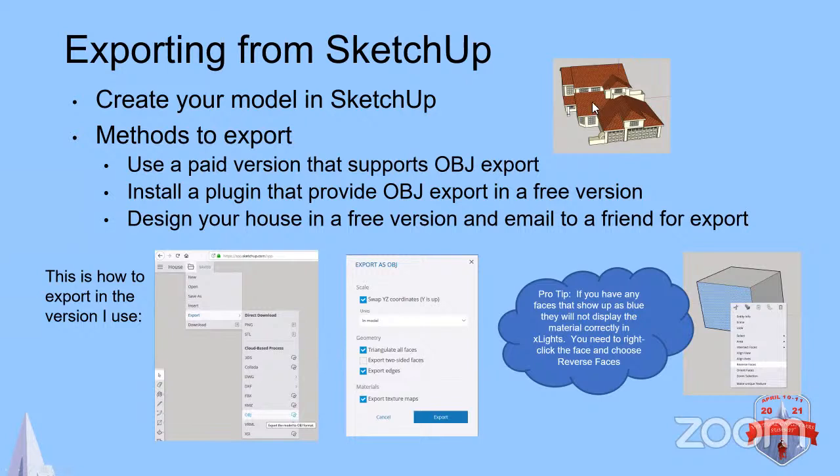Texture maps, if you want any of the textures, like you see I have a roof texture on mine. If I want that, I need to export that texture. And you don't really need to export two-sided faces. That would mean all the inside surfaces that I can't really see would get exported as well, so you'd have all your inside and outside textures.